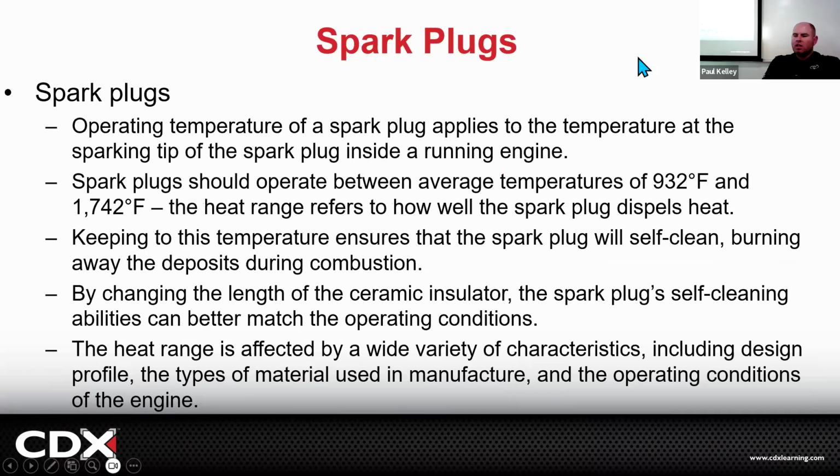And then we start talking about the heat range. This next picture will make sense. So typically we're running around 932 to 1,742. Okay, that's the spark plug's typical operating range. If the temperature gets too low, the spark plug won't self-clean, right? Basically, if you think of the carbon and the fuel, it kind of coats it. Like, you guys ever use a fireplace with a glass front? If your wood is wet and your fire's kind of cool, it'll get sooty in there.